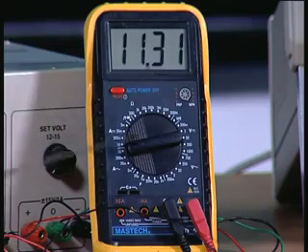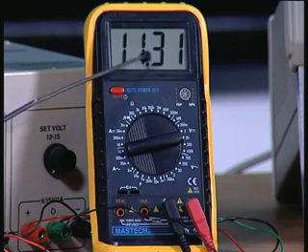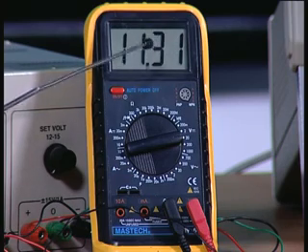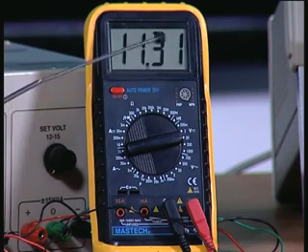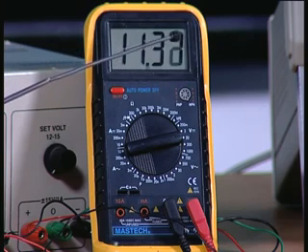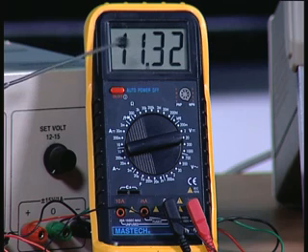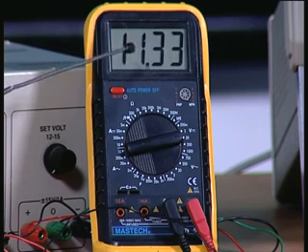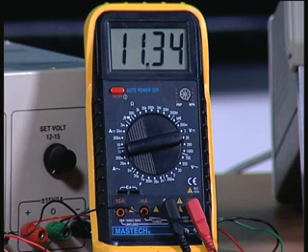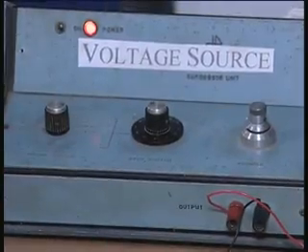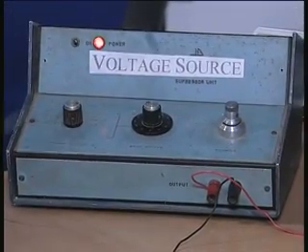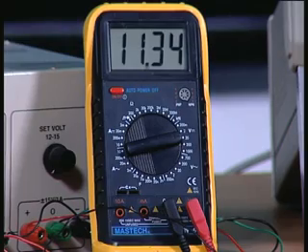The multimeter here is in voltage mode, and it now shows 11.31 volts. That means it is positive. That means my pin number 2, which is the inverting input, is lower than the 1.2 volts, and therefore I am getting positive VCC here, nearly 12 volts. If you look at the dial, you can see the voltage here is indeed about 1 volt, and therefore it is less than 1.2 volts, and that is why you are getting 11 volts.